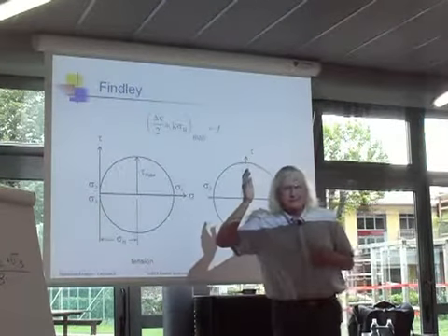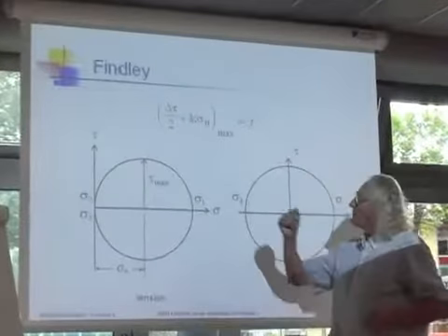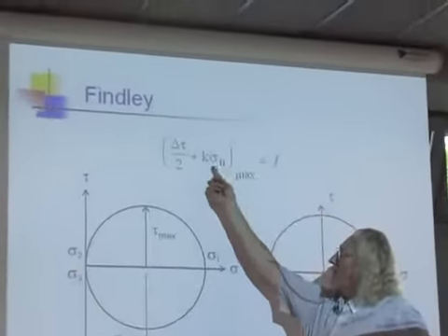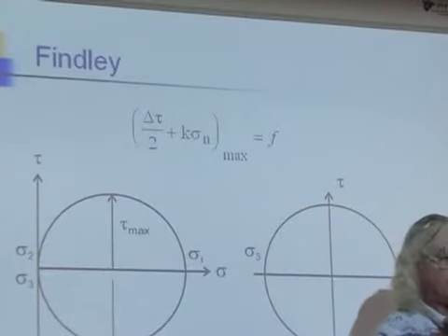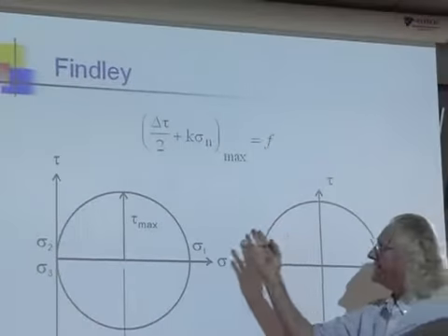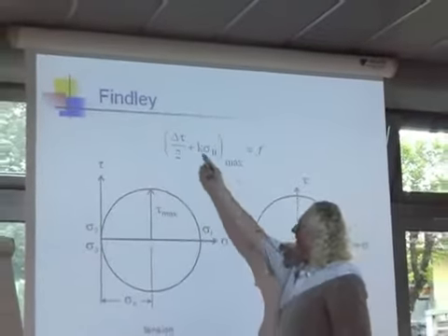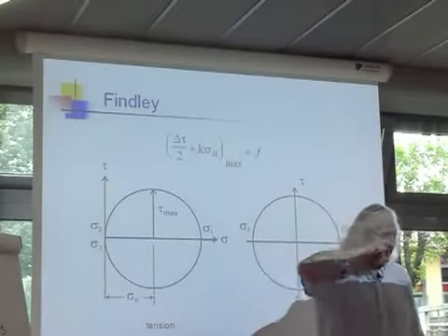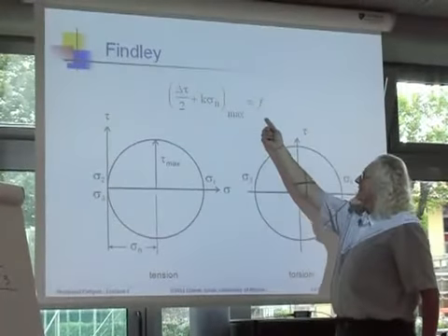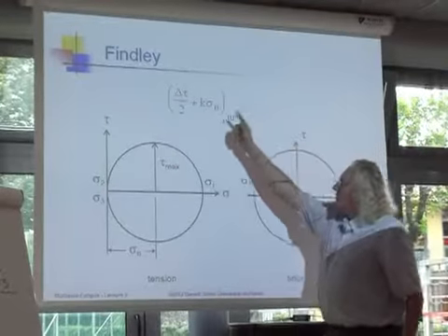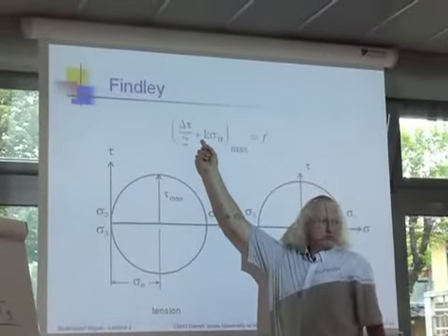Sure, why not? You know, maximum stress in a grain makes a lot of sense. But the normal stress will also have some effect. The magnitude of the normal stress. And he, of course, combines this in a linear way. And, of course, with a scaling constant K in it. And then you set this to the fatigue limit that you like in tension. Again, normalized back to the correct value of the shear stress.